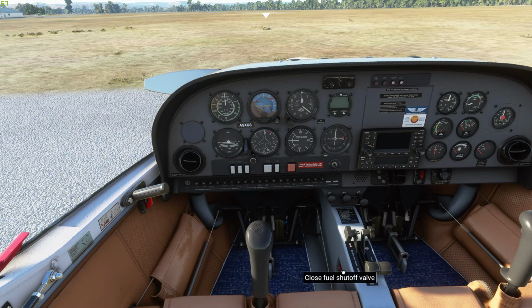So that's about it. Essentially all aircraft are going to have maybe 4 or 5 different types of systems or some component thereof. Obviously you're going to have an electrical system, which is what you need for your radios and to start the thing up. Some aircraft are going to have a pneumatic system, so that's anything to do with air. That could be used in brakes, pressurization, bleed air from the engines, and all manner of different types of systems that use some form of pressurized air. You're going to have hydraulics in some aircraft, which we use generally for flight control actuation or landing gear retraction and extension, maybe flaps sometimes.